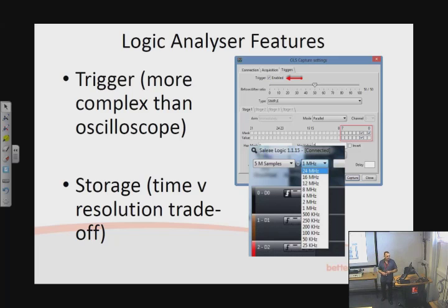The logic analyzer allows us to take that a little further, and we can configure an exact sequence and also an exact pattern in parallel across several devices. So we can sit there waiting for a particular thing to happen and then start recording automatically. In other words, we can set up very elegant and sophisticated triggering scenarios.